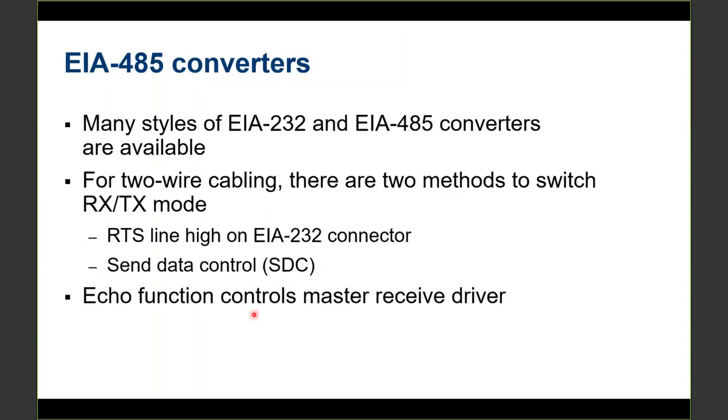The echo function controls a master receive driver. If you're using two-wire and sharing that comm network, and you do a transmit, if you turn echo on, it's going to leave your receive on, and in the device you're going to receive all the data that you're transmitting out that was meant for the other end.